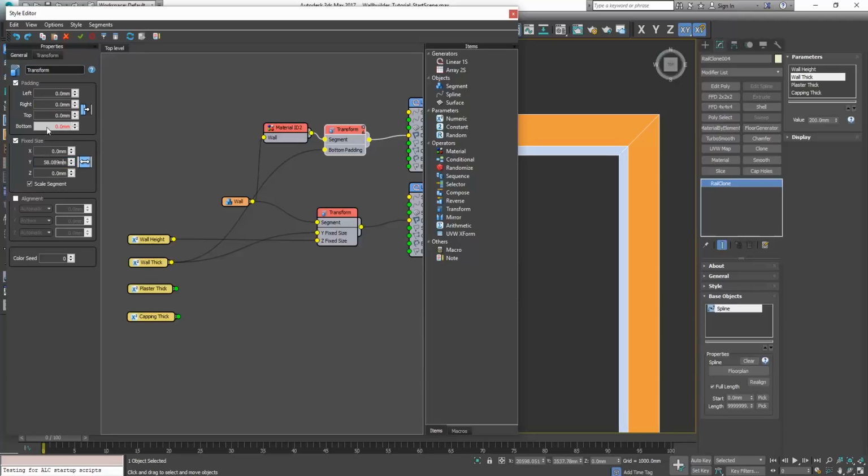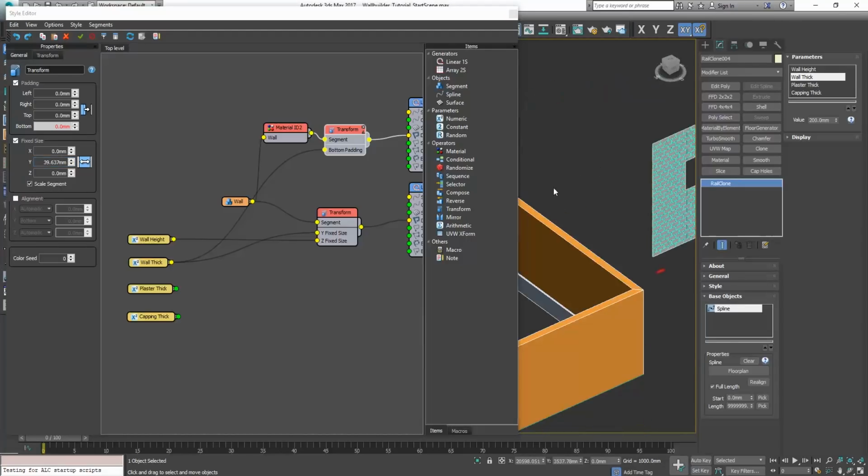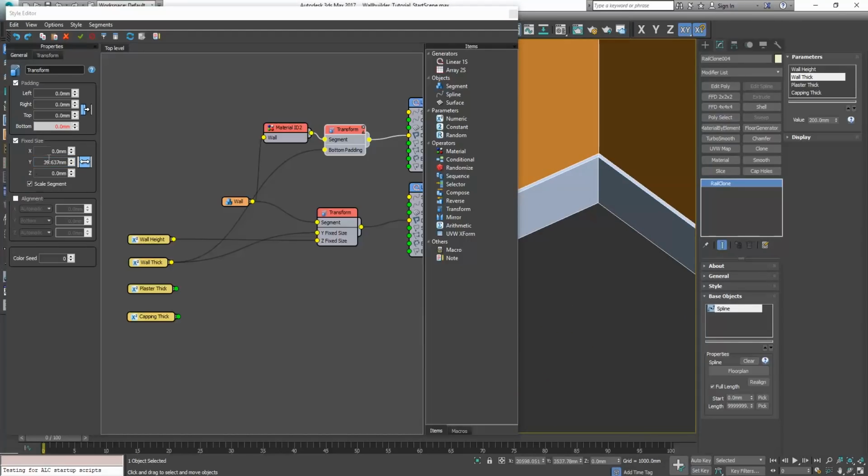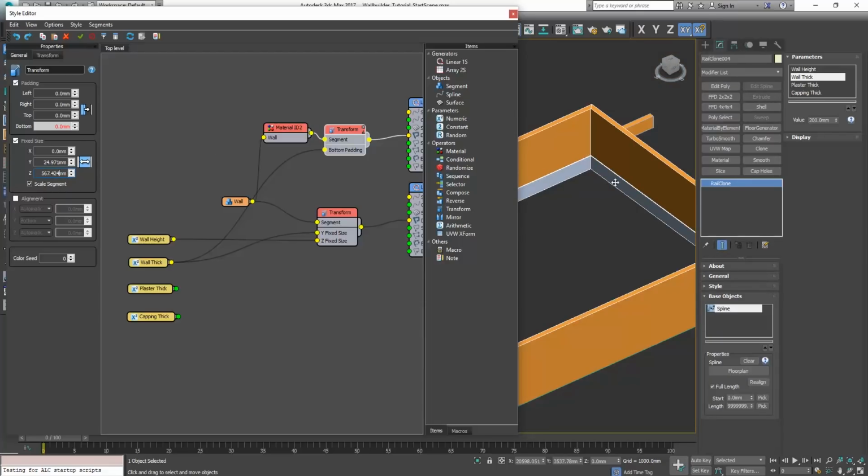Alright, cool. We want the Y size to be controllable. We'll call that the plaster thickness. And the Z height should pretty much match the external wall, unless you want it different for some other reason. So let's expose those two.